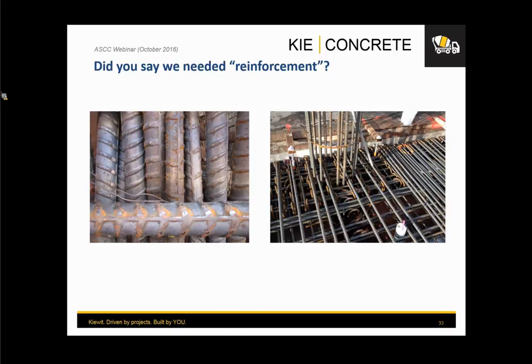This is the fact. This is how we build work. These are the things that you see in the field, right? And these are things as required by design. There's no contractor that is going to put more rebar than what they need to put, right? So this is a really challenging effort. How are we going to achieve the right consolidation process here and achieve the right product, with a mix that is going to flow through all this amount of rebar and achieve the performance they intend with the design, right?